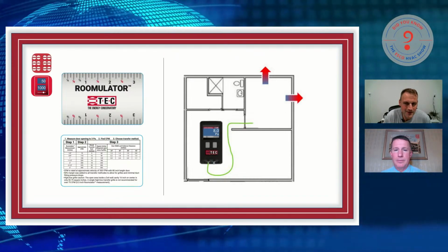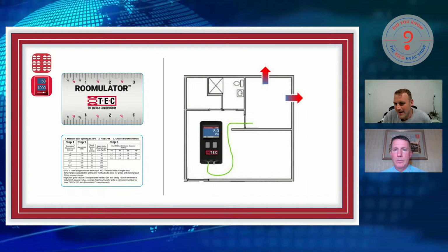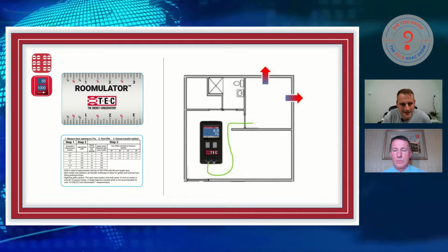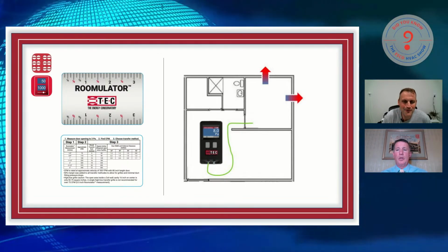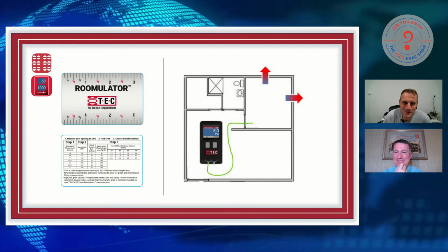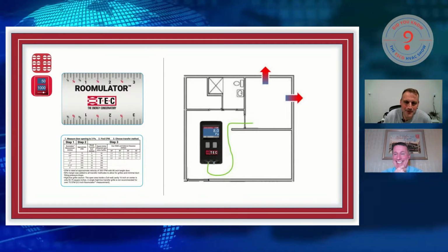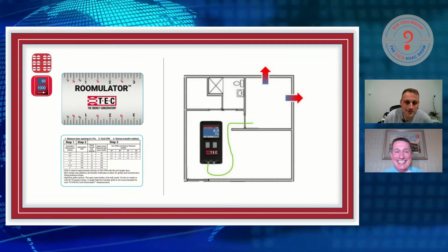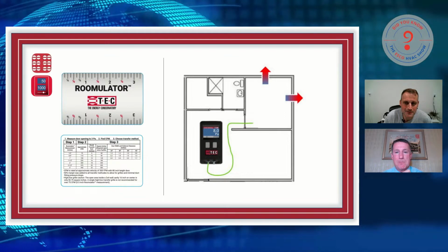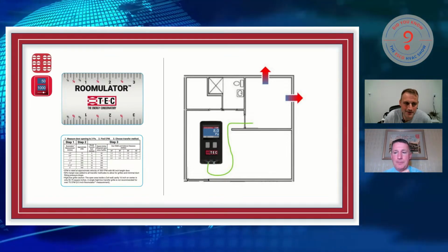Here's what I'll tell you. I didn't want people searching for K factors of grills or anything like that. This needs to be something quick and easy. A friend of mine would say, keep it simple, stupid. So that's exactly what we did with this. There's 50% margin built in for a 90, 2 grills, 1 on each side. All that's built into the measurement.